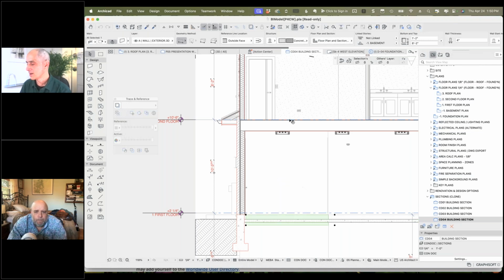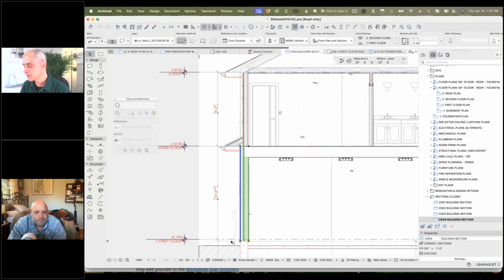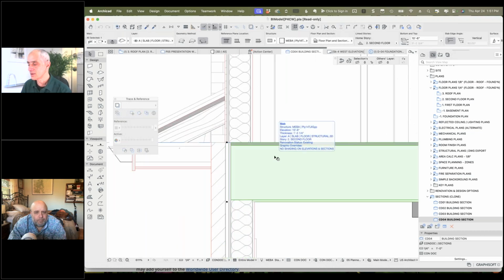Okay. All right. Now, again, always trying to bring out some useful nuances here. The wall is actually below the reference line of what you called out as the first floor in this case, but it's going from floor to floor, and it is being interrupted by this slab, which has, of course, the finished floor, the space for the framing, and the drywall ceiling here.